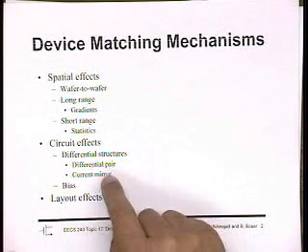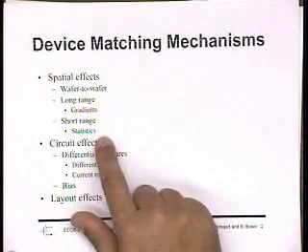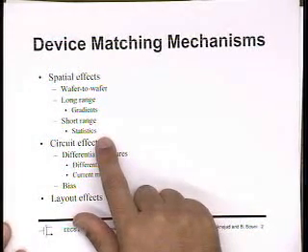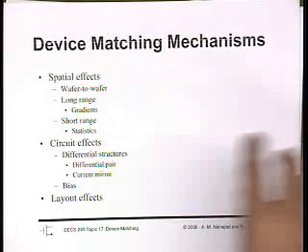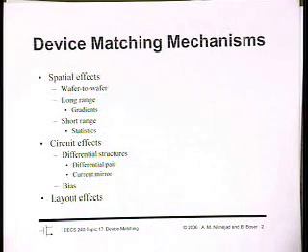What we're really concerned about, though, is short-range effects, because we're not going to build a diff pair by putting one transistor here and another transistor a millimeter away. We're not that stupid, right? We're going to put them right next to each other.